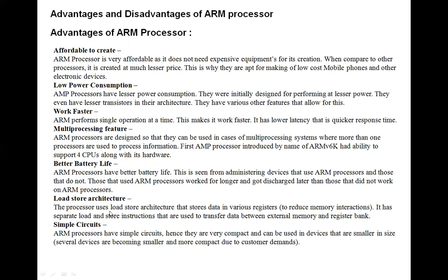Then a load store architecture will be there. The processor uses a load store architecture that stores data in various registers. It reduces the memory interactions. It has separate load and store instructions that are used to transfer data between external memory and register banks. So this is the beauty of load store architecture.